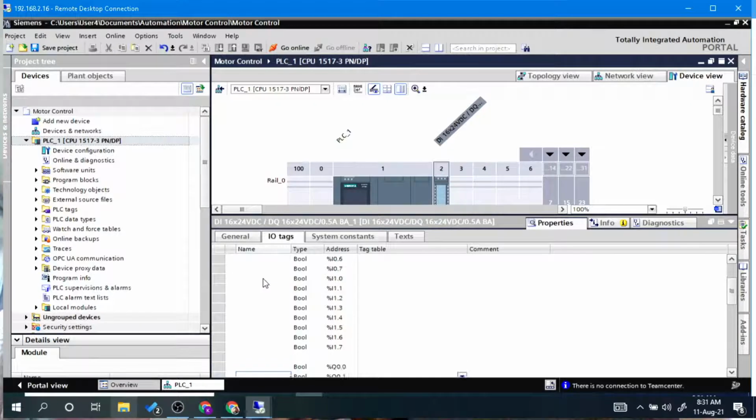So that's the difference. Practically, most of the time you have feedback, and then you have a motor. Nothing much here. You might need sometimes an indication for a different output, like the motor is actually running, to show that. But usually that happens from the contactor. So the contactor will have an auxiliary relay contact, and from there you connect the indicator. I'm not adding that one, so I just wanted to say the difference.